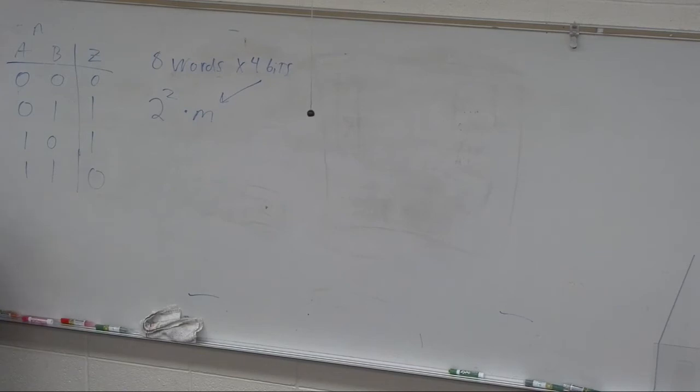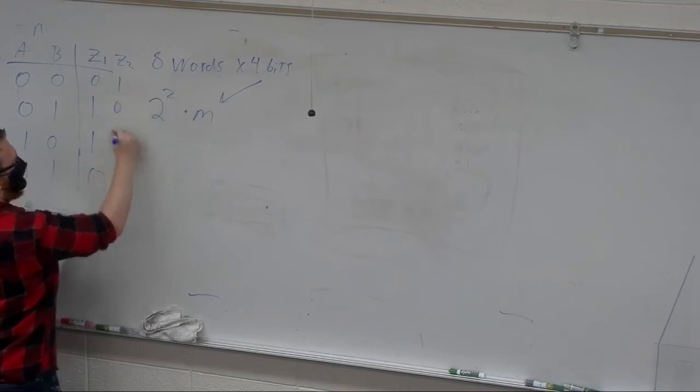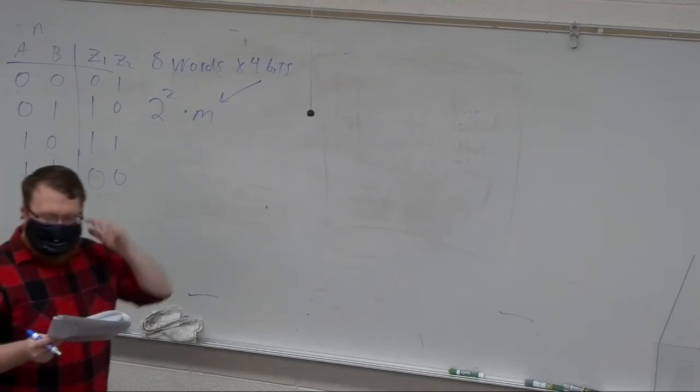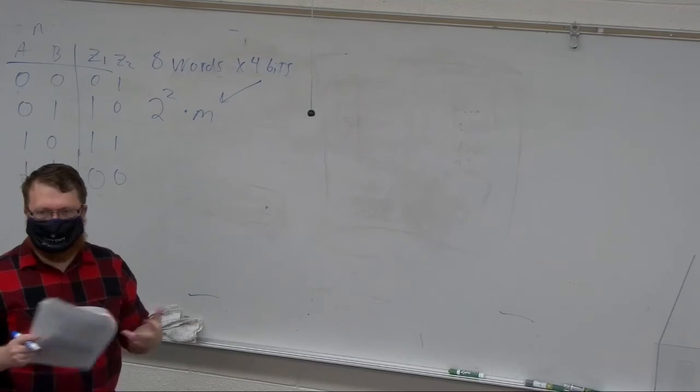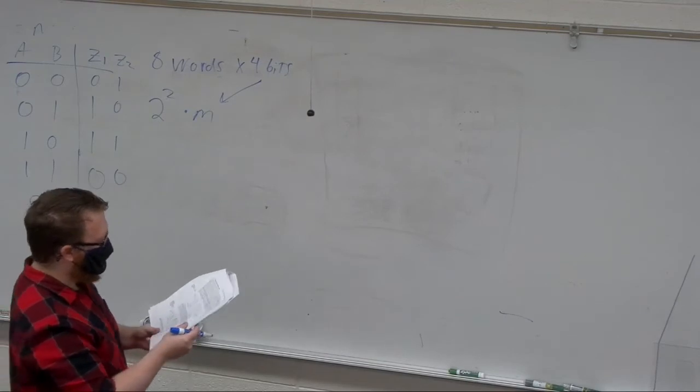We can go on and do something bigger. The word is in direct relation to an output. So that's a word, that's a word, that's a word. But you could have something that has other outputs, that you have a Z1 and a Z2. So in this case, I'm programming a XOR gate and something else that is doing a lookup. But you can even go in and start programming something like a full adder or an encoder or something like that, that starts to get a lot bigger.